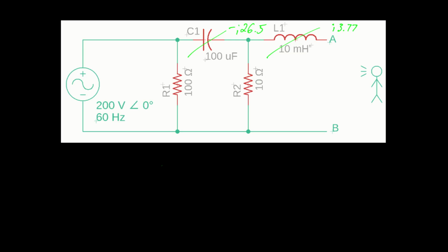the inductor. To calculate the Thévenin impedance, one of the things we do is we assume that that power supply is shorted. Keep in mind that when we conceptually short that power supply, we're also shorting out R1, so R1 does not exist. What we see then is from terminal A, we see the inductor, and then we see the resistor and the capacitor in parallel, yielding a Thévenin resistance of 8.8 plus J 0.5.